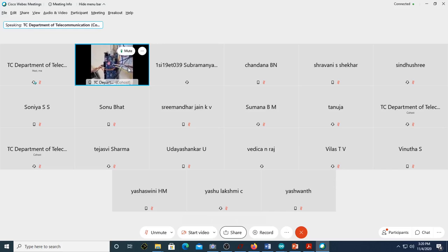Okay, now can you see the Arduino? Yes, sir. This is how the Arduino looks. So this is Arduino Mega. This is not like Uno. Uno has got a limited number of pins, that is 14 digital IOs and 6 analog inputs. But here in this Mega, it has got 53 digital IOs and 16 analog inputs. It has got a bit extended number of analog and digital inputs and outputs.